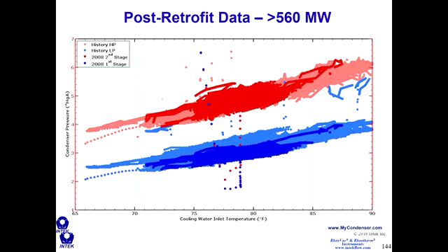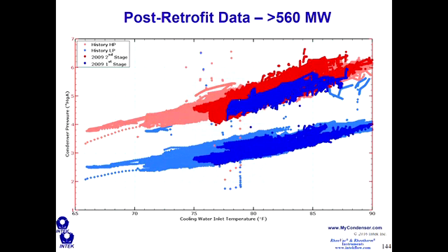Here's 2008 data, the whole year of 2008. In 2009, the condenser had a vacuum pump problem, so they had to vent or exhaust both shells using one vacuum pump. So the LP shell and the HP shell became common pressure for a short time, and so that's why you see the LP shell operating up at the HP shell pressure.